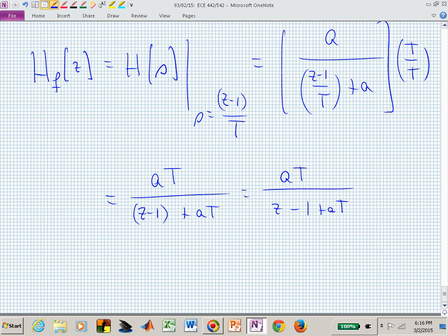And that's now a discrete time transfer function that's a low-pass filter, and you could create a difference equation. You could implement this in Excel, in some microprocessor, if you took this Y over Z relationship back into the time domain, using these coefficients, little a, capital T, etc., where Z is an advance of 1.